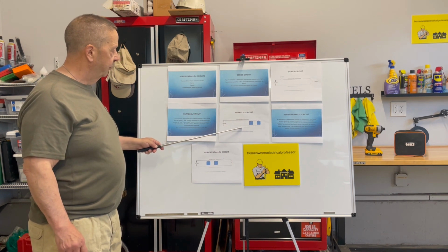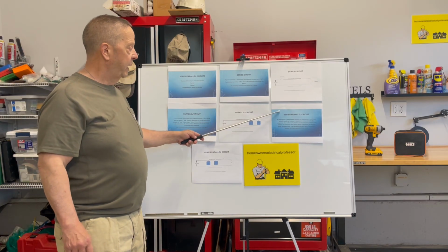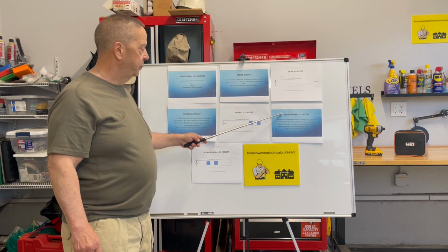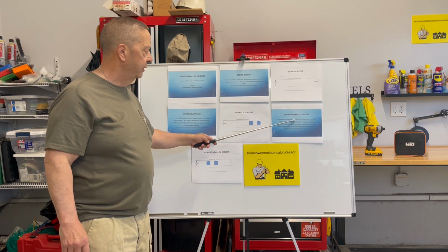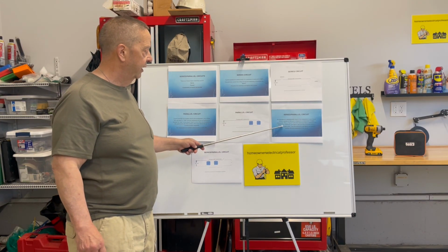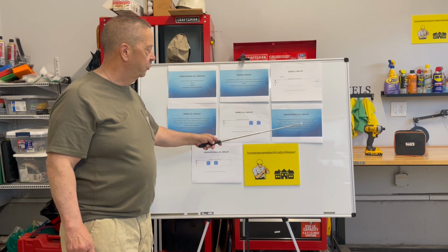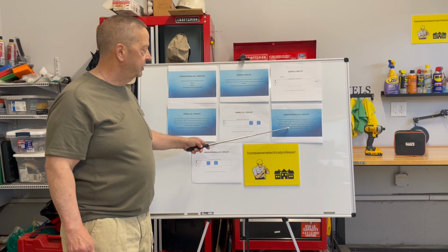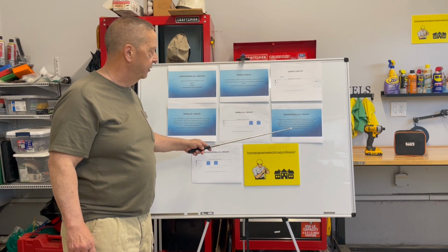A series parallel circuit, an example of a series parallel circuit is the receptacles in your house wired in parallel so that each receptacle is independent of other receptacles. Then a branch off of the circuit can feed switches and lights. The switches and lights part of the circuit are wired in series with each other. The switches and lights are wired in parallel with the receptacles in the circuit.